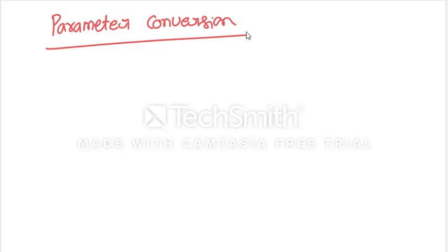One parameter, other parameter means. So now you tell me, if I know z parameters, can I get y parameters? How? Here this y matrix is equal to simply what now here? The inverse of the z matrix, isn't it?